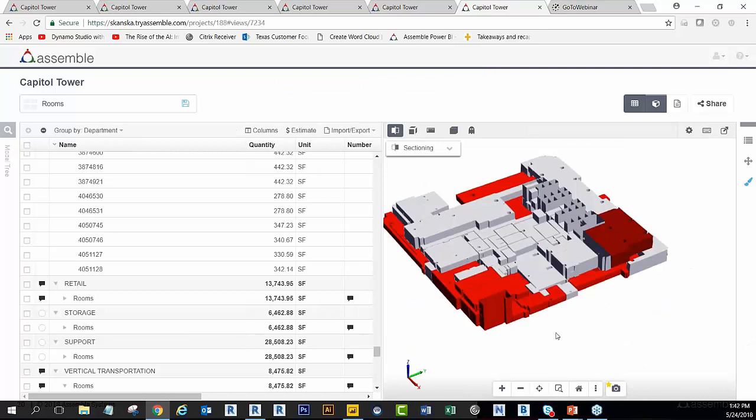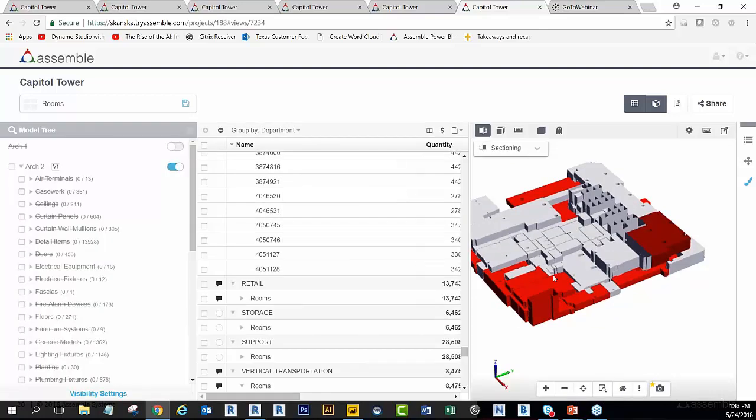Another thing you could do, once you've added that: usually I leave the colors on so I can see it, but you may be able to go into the visibility settings and say, if you've got a parameter, only show information that's showing blank versus the other information, so it starts to hide part of the model as well. So that's a lot of flexibility you're showing, whether you want things color coded as you go or shown or hidden as you go.